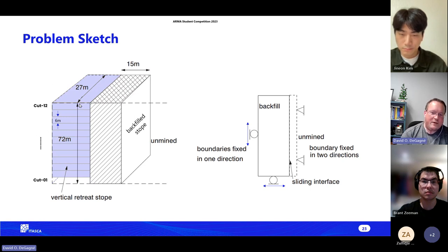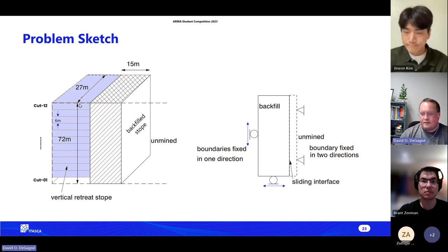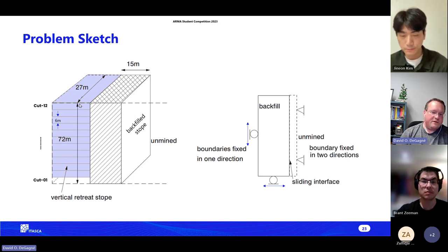That's just because the load is artificially, in an uncontrolled way, being applied to the sample, and it explodes. And so that can happen in a numerical model. If you just all of a sudden have a model that's happy, stable, in equilibrium, and then you make a giant opening all at once, then all that material wants to rush in really quickly. You can get all sorts of artificial dynamic effects that will create artificial yielding and numerical instability in the model.